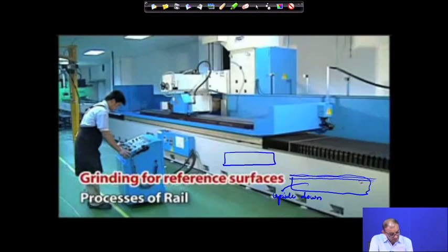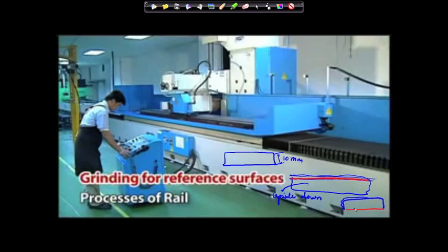Correct. So, now we have created this reference surface. All the dimensions you want to machine, suppose it is 10 millimeter, then the 10 millimeter will be counted from that location. So, now this is your reference surface, and you have reached this location. Now, mount it upside down. So, now your surface is something like this. The top surface may again be very uneven, but your bottom surface is completely flat, because you have taken it as a reference surface.